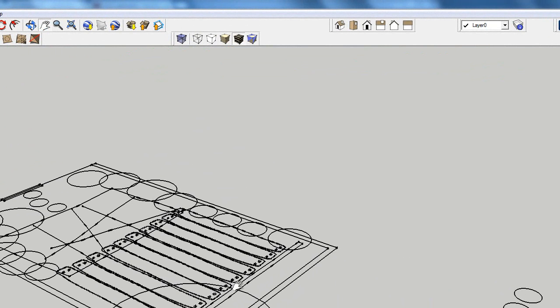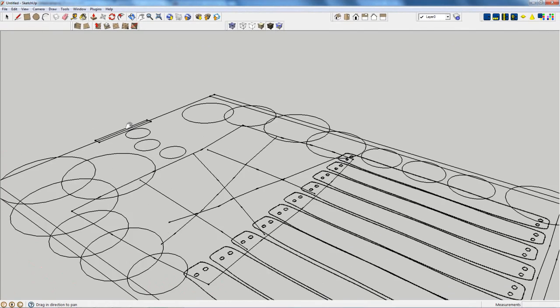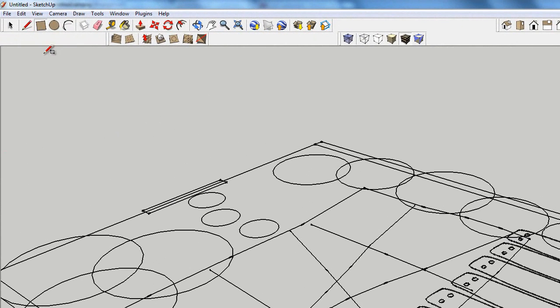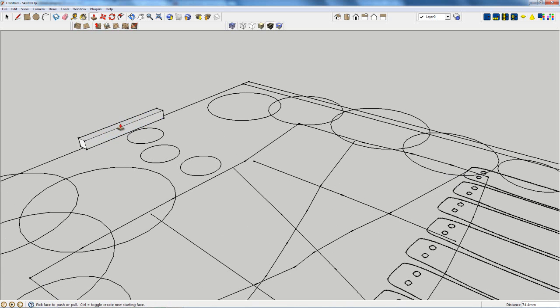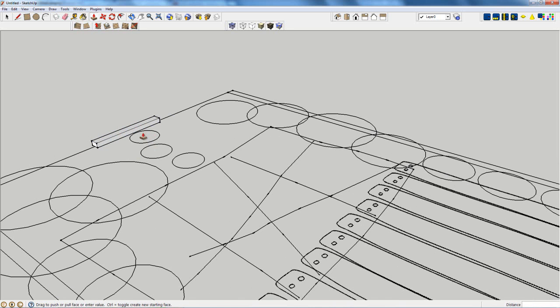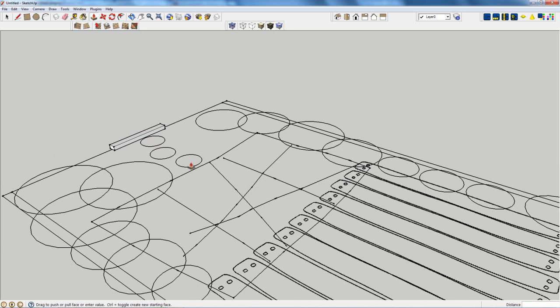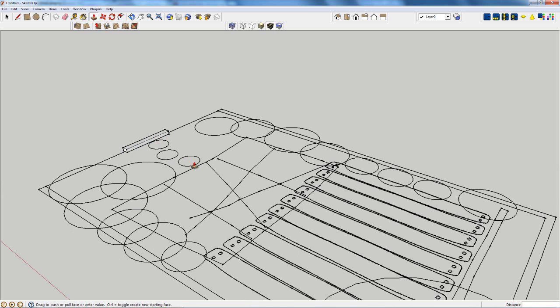So here's our design. You may remember we had a rectangular step at the beginning. So it's a very, very easy matter to pick SketchUp's rectangle tool, and the rectangle just attaches itself to that step. We could use the push-pull tool and say, let's zoom in, and we'll make that step, say, a 50mm high step. So we're building our 3D model. These are little stepping stones, wooden stepping stones or whatever, that move through there. So we can use any of the SketchUp tools to draw in this environment, and because the geometry is already there, it becomes a relatively easy thing to do.